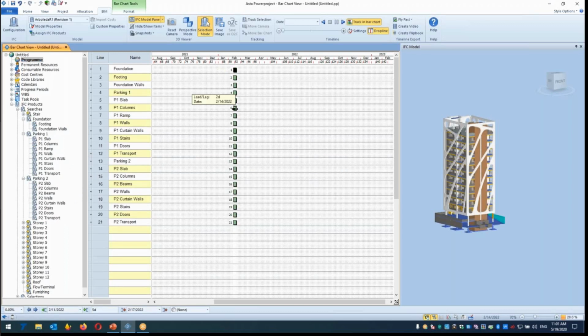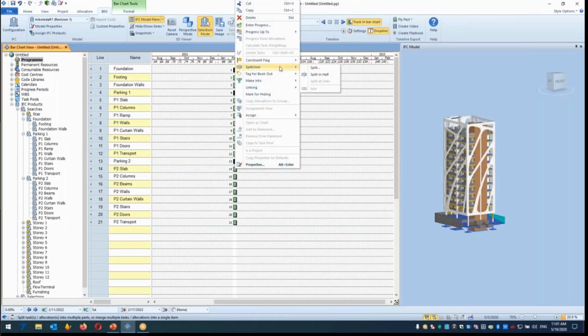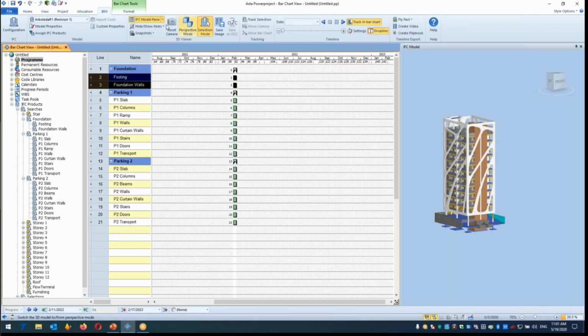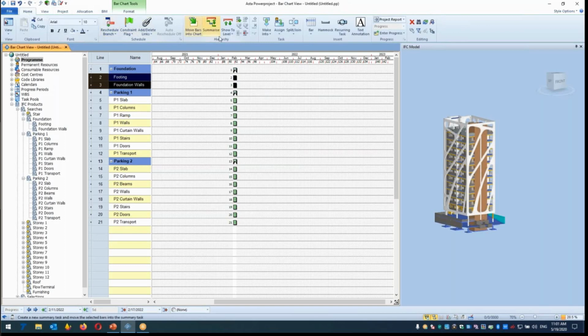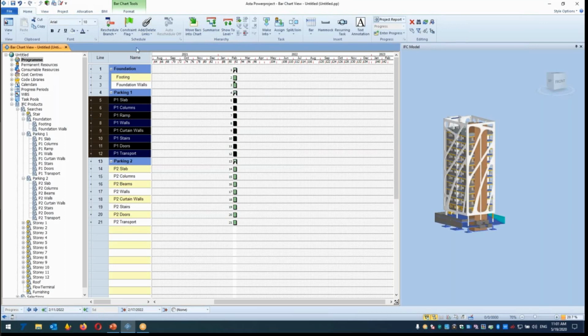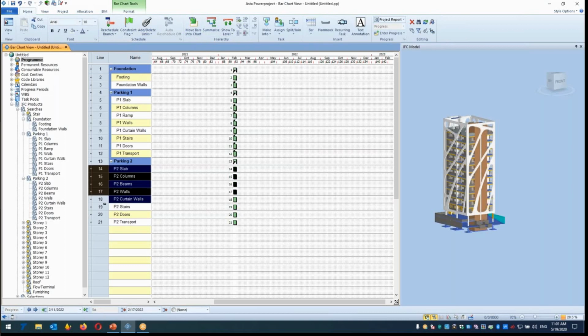And then when you create this task, it has to be linked. Foundation is a work breakdown structure, parking is a work breakdown structure, and the parking work breakdown structure is made here as a summary task. So for the footing activities, you go here and say, okay, this is here, and you link those tasks. This task you select and say belong to here and link the task. Here we select belong to here and link the task.